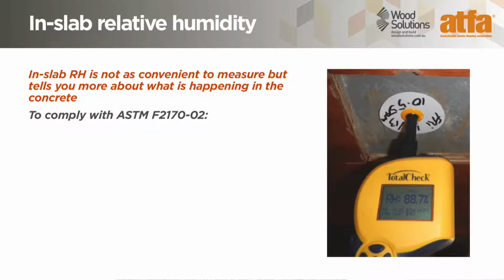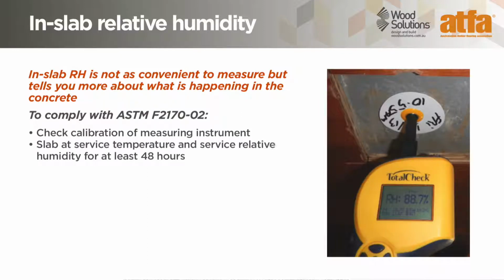To comply with American standard ASTM F2170-02, the following is necessary. Regular checking of the calibration of the measuring instrument. The slab is to be at service temperature and service relative humidity for at least 48 hours.